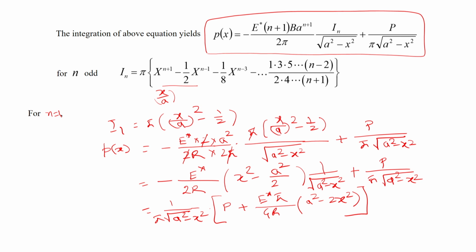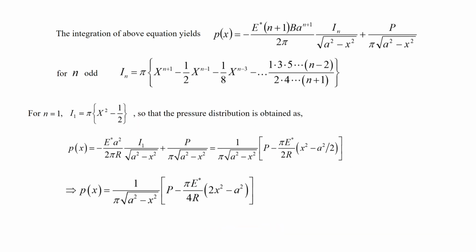So, like that, the pressure distribution that will lead to that kind of deformation profile is something like this, right. Here I have taken the minus sign, so that is fine. Now the question is, what is A? Px is of course defined, but what is not known is the value of A that will be attained in this particular case. Capital P is known; capital P is the amount of load that has been applied.